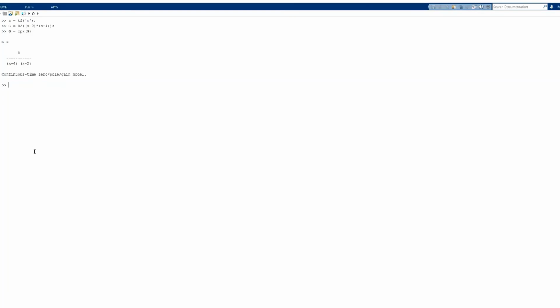K1 is for sure larger than 0. That's actually the condition. So if I say K1 is just 1, just larger than 0, that's actually met, I can now play around with K2. I know that the expression for K2 was K2 is 1 over K1 plus 0.5. That was the expression, and this is what we have discussed. This is actually the edge of the stable point. So if you have K1 equal to 1 and you make K2 exactly 1.5, you will have the marginally stable system. If you want a stable system, then you need to make K2 larger than 1.5.